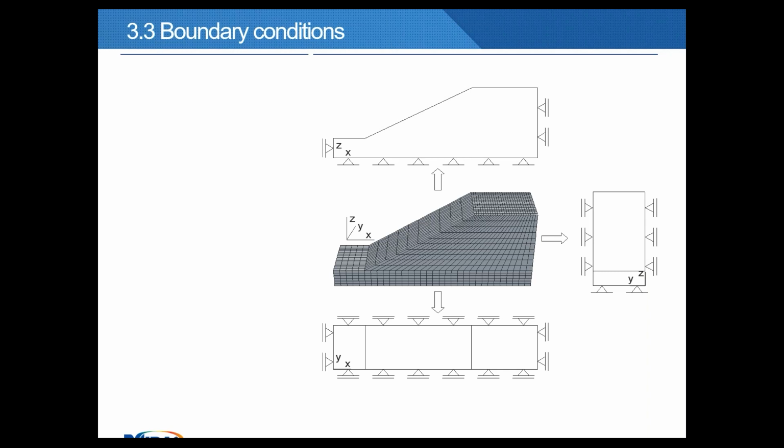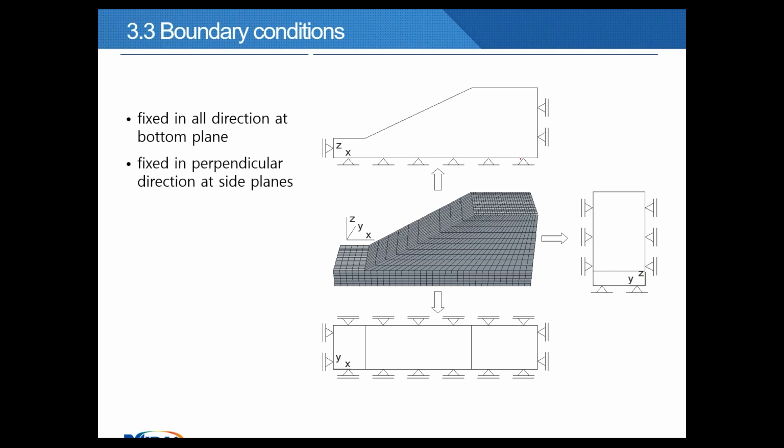The proper boundary condition in this model is also fixed in all directions on the bottom plane, and fixed in the perpendicular direction at the side planes.